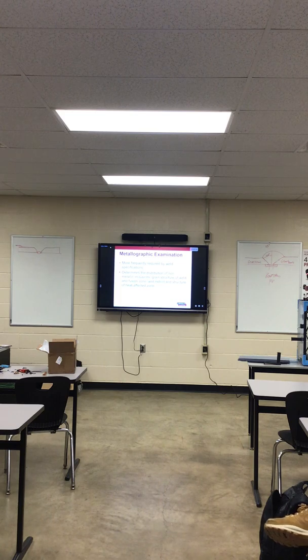Metallographic examination determines the distribution of non-metallic inclusions, grain structure of the weld and fusion zone, and the extent of the structure of the heat affected zone. Okay, what this is telling you is how much have you changed or modified that original grain structure of that material that affects the strength and rigidity of that piece, correct? That's why you don't wanna quench it in water either. Certain processes, yes, you do not want to quench it in water.